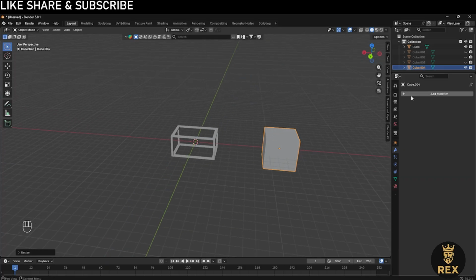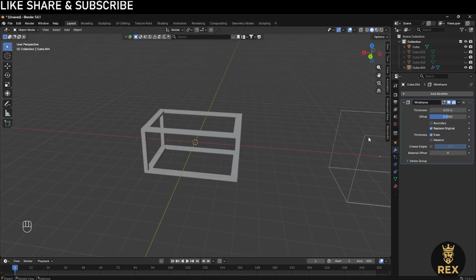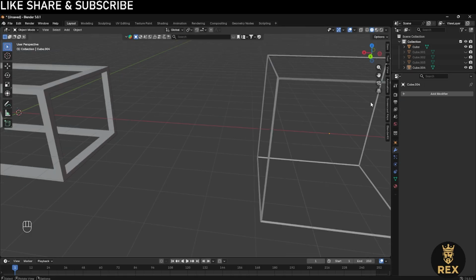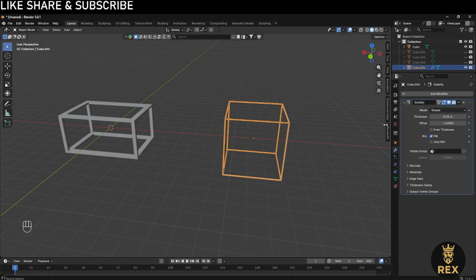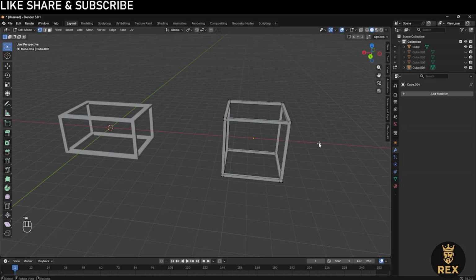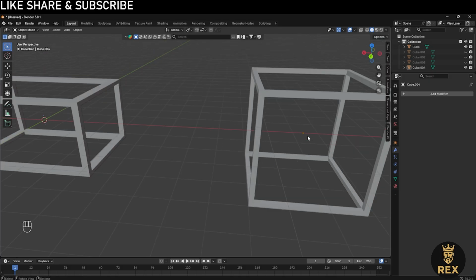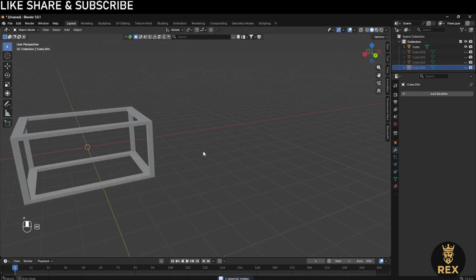Let's move it to this side and scale it. Then add a Wireframe modifier here. You can see you can add thickness here, and as you can see, thickness is added to this. Now apply this. There is also the Solidify modifier, you can use it and get the same result, but I use this. I tell you both methods, it's up to you which method you are going to use. I'm not making you bother.